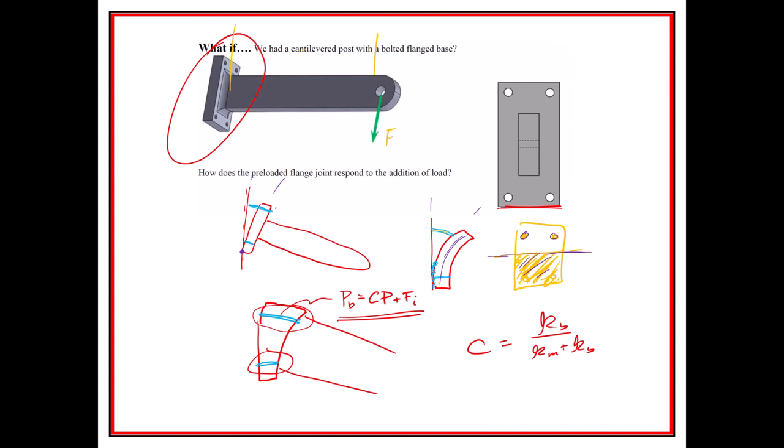And this is one of our most challenging aspects as engineers, mechanical engineers dealing with solid mechanics problems, trying to figure out what the appropriate loads are. So which one of these is correct? That's a good question. I don't know. Is there going to be an answer? We could run an FEA on this, and that would definitely give us more information, but it wouldn't necessarily say that that's exactly how the bolts are loaded. It's an interesting problem, an interesting dilemma.